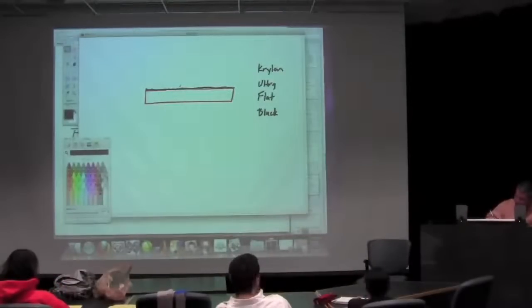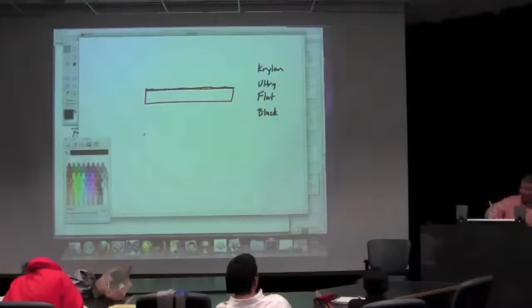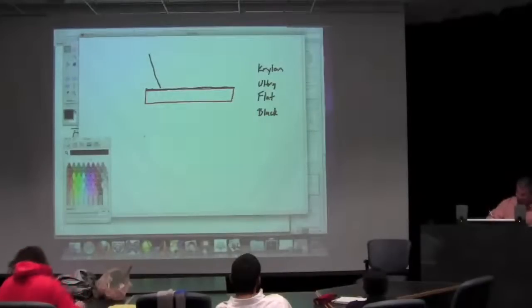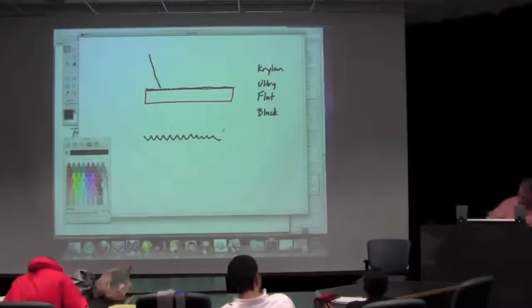Now, the other thing you can do is you can roughen the surface. Okay? And what's the whole goal here? The goal is to reflect no photons, right? High emissivity, or an emissivity of 1, means the reflectance is 0. So all the photons that come down onto here, I never want them to leave again. So if I paint it with a paint that's emissivity 1, that'll happen. But if I don't have that, if I texture the surface, and particularly if I sawtooth the surface, right? So let's say I sawtooth that surface. Now let me blow up one of those areas like this.